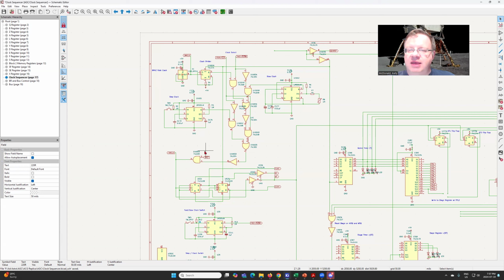We also have a halt control signal, so if for whatever reason the computer needs to stop the clock, we have that option. Then we have our 4 megahertz divided clock that comes out here. And these are our 2 interconnected JK flip-flops that produce the 4-phase clock.